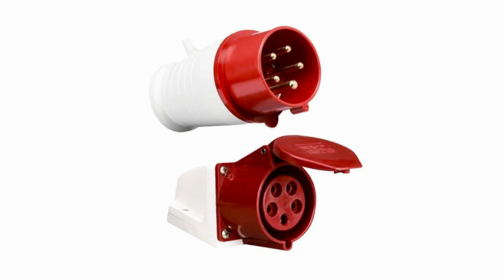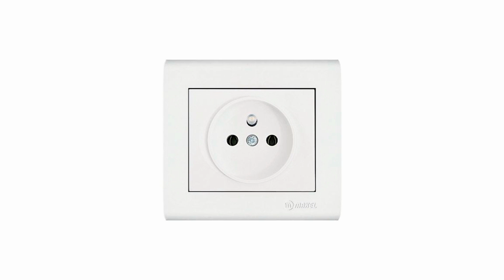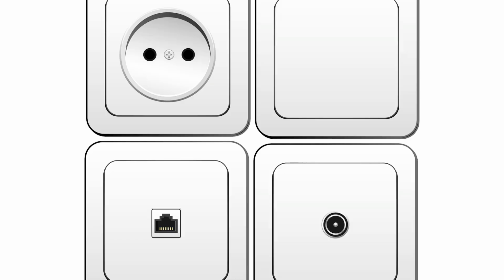The 5th is the 3-phase socket, which is mainly designed to handle 3-phase load, such as the welding machine, drilling machine, etc. Their current ratings actually depend on the load. The last of them all is the UPS socket, which is designed for computer loads.